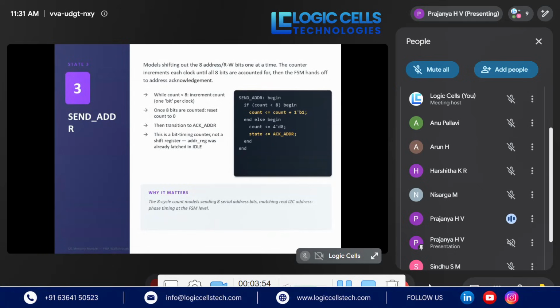The counter increments each clock until all 8 bits are counted, and once the 8 bits are counted, it resets the count to 0, then moves to the acknowledgement of the address.